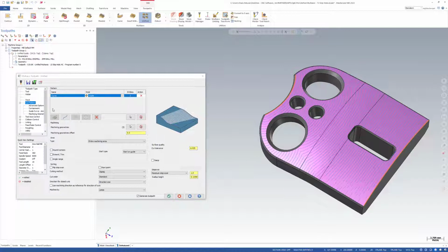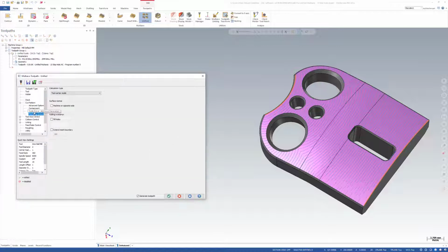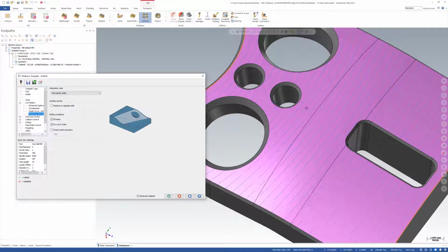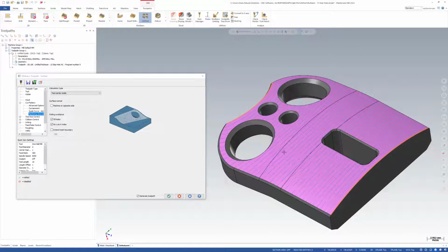However, with Morph, we lose a lot of these extra options that we like. So what I can do here is say fill holes with no cuts and holes. So now Mastercam basically created fill surfaces inside of these holes, and the toolpath stepovers are cleaned up.